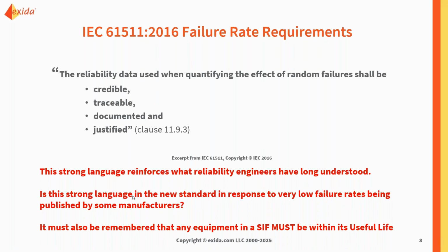We have to follow the useful life. And that's because during useful life, we are justified in claiming a constant failure rate. Once we get outside of useful life, the constant failure rate doesn't hold true. So our calculations will not hold true.